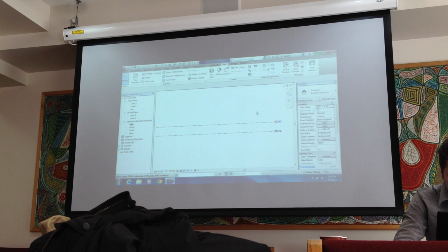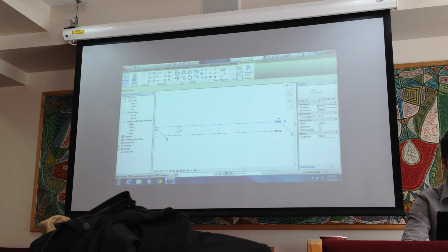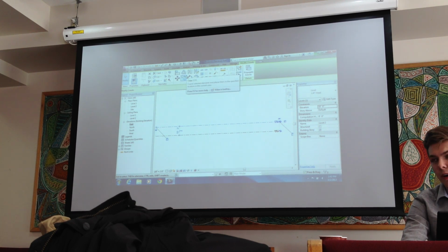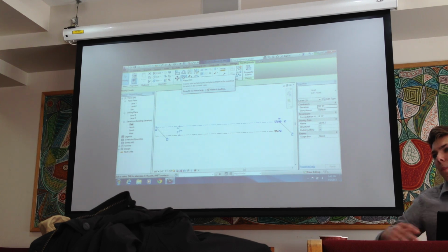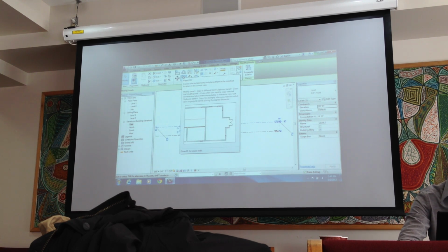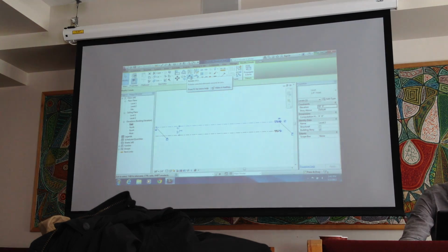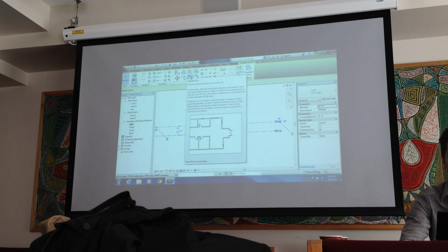So there's 2 ways to add a new elevation or a new floor. You can copy and paste it. If you click on it, you'll see the modify tools that automatically locate. So there's a line tool which will allow you to line walls and flooring together, offset, mirror. A lot of these are things that AutoCAD has as well, just this naming that they have, so it's pretty easy to understand how these work if you know AutoCAD. But if you don't, just highlighting over it, it'll show what each tool does again.